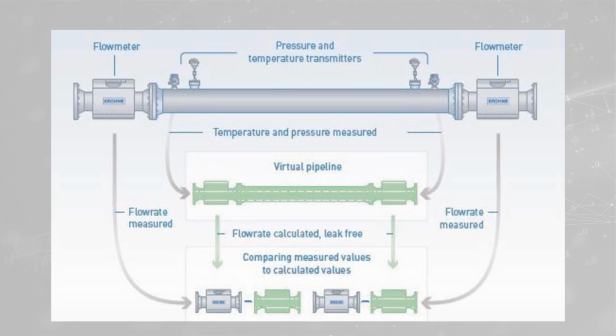Mathematical modeling can be organized as follows. A real pipeline that has all the real sections, including the measuring stations installed, and a virtual pipeline that has all the sections, including the installed metering stations, and the virtual stations, where the operator wants to have measurements. Using the Kalman filter, or one of its extensions or variations, the value of state variables in virtual stations can be estimated. In this way, the profile of the operation is formed throughout the entire pipeline.